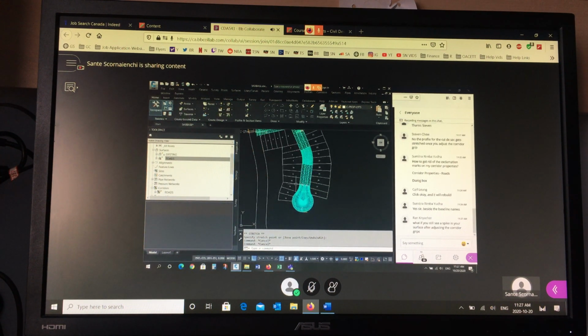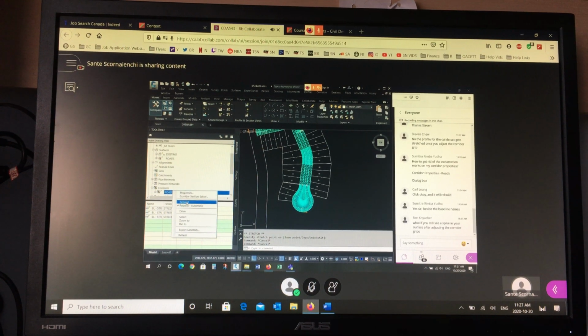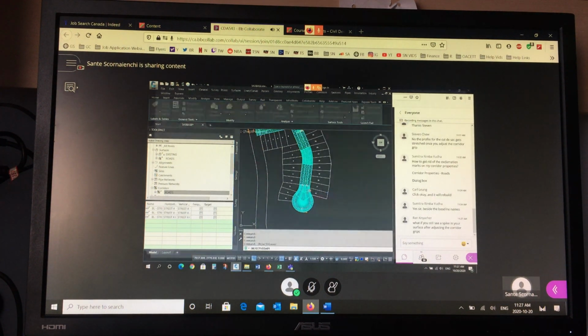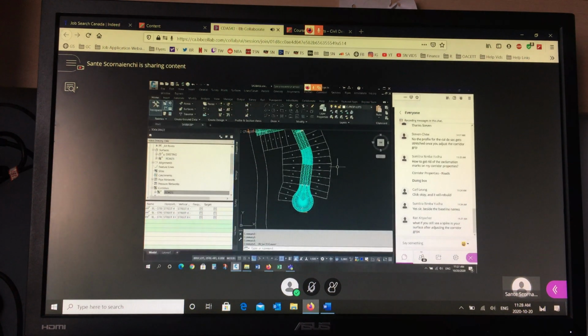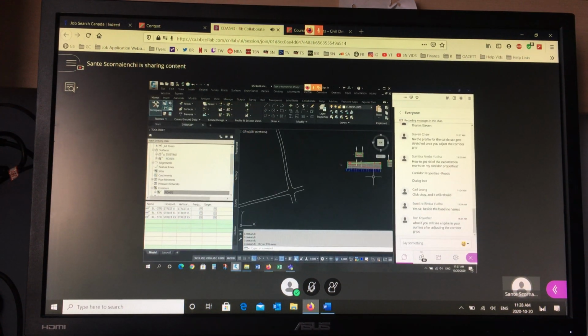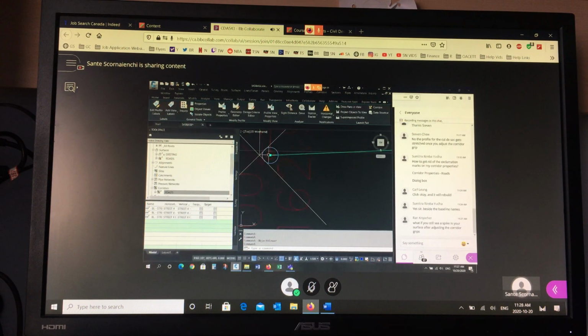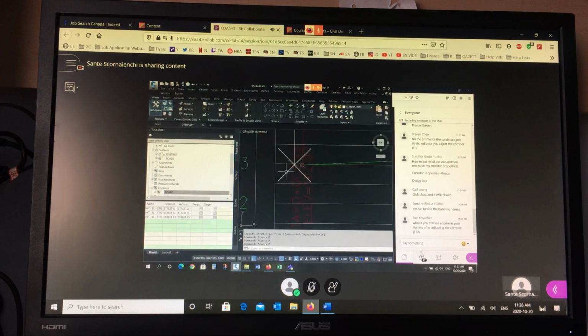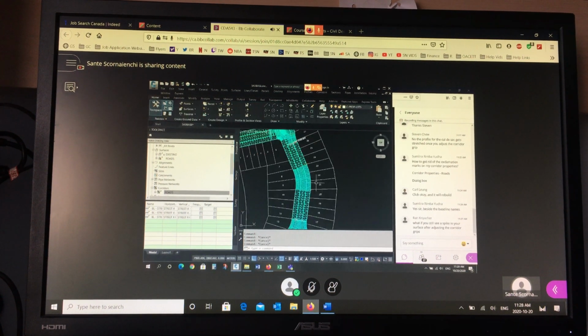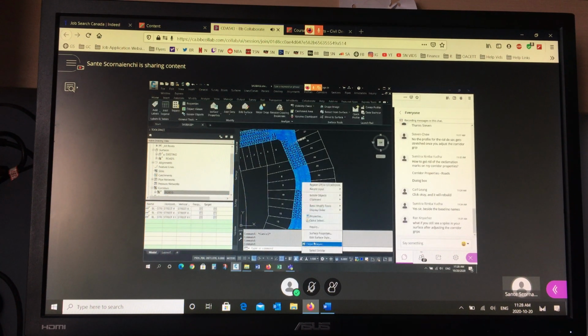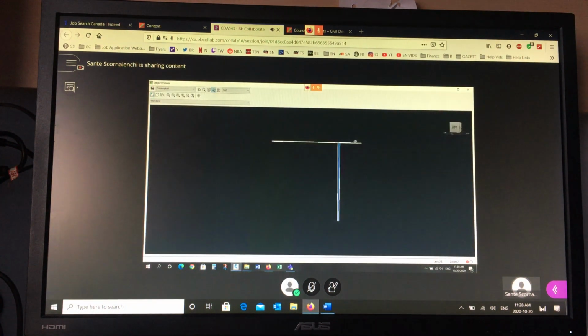Watch, I'll show you. Let me rebuild the corridor. Let me show you the surface. I've got a spike on my surface for sure. Oh, maybe not. Should have created a surface spike. Let me show that again. If this doesn't quite match, sometimes it gets finicky. Right, so it's supposed to be over here. I'm modeling from here over, so it should have created a spike in the beginning. Just check it. Rebuild. Yeah, there it is. Right, so that's the problem.